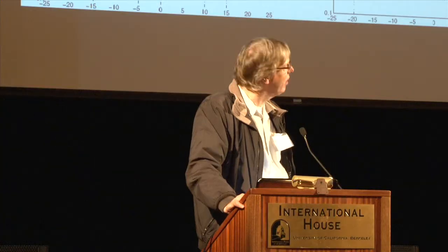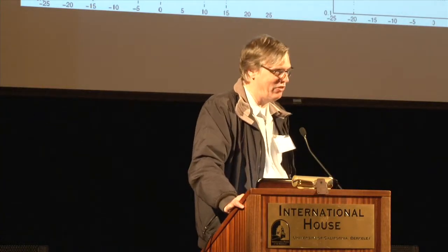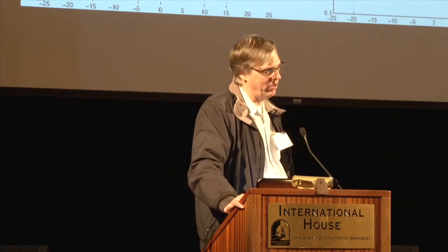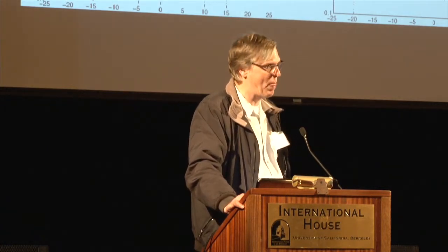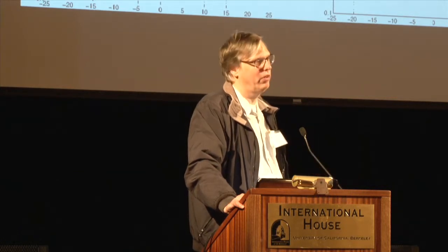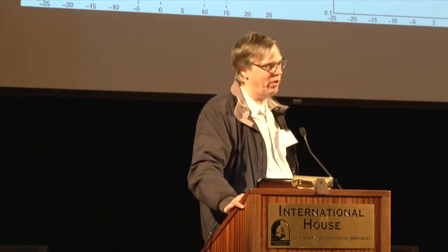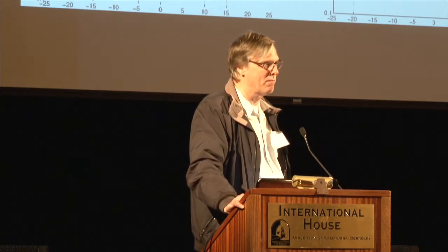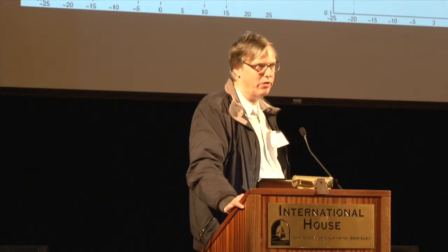Right, and I really condensed Doug's presentation dramatically. He was focusing on the radiation pattern on the longer period parts of the evaluation. Here, our main interest in hanging wall effects is at the shortest period, because empirically that's where it's the strongest. But you're right, if you randomize a radiation pattern, then they all have the same geometrical effects in them. Other questions or comments?